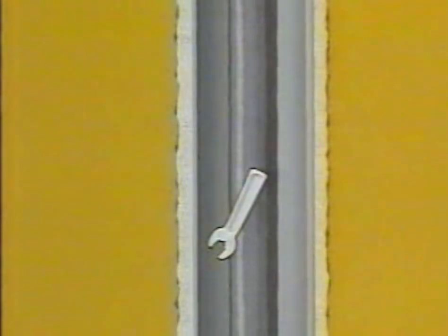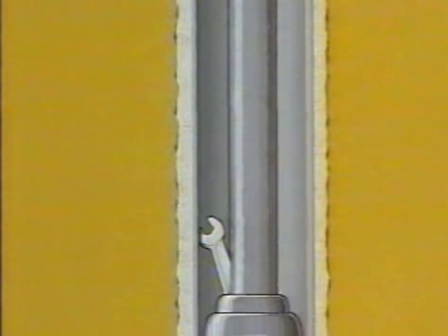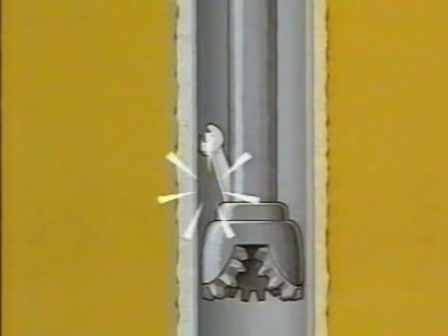Any objects which fall into the well from the rotary table can quite easily jam the drill string. Even a PDC cutter, for example, is large enough to do this. Consider the clearance between a 9 5/8 inch 47 pound per foot casing and an 8.5 inch stabilizer.